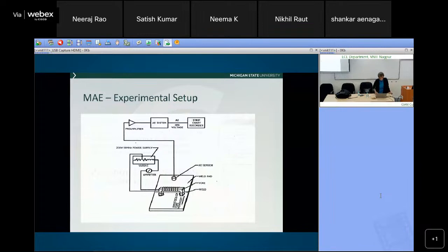Although, again, what I said was the pickup signal is in the acoustic frequency range. You don't have to magnetize at that higher frequency. You can, at 50 hertz, exactly. That's why the acoustic frequency is much higher than the excitation frequency. I didn't say 4 kilohertz is for the excitation signal, but it's the pickup signal.